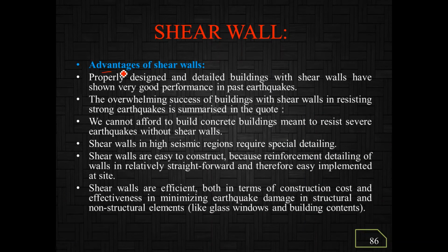Properly designed and detailed buildings with shear walls have shown very good performance in past earthquakes. The overwhelming success of buildings with shear walls in resisting strong earthquakes is well documented. We cannot afford to build a concrete building meant to resist severe earthquakes without shear walls. Shear walls in a high seismic region require special detailing.